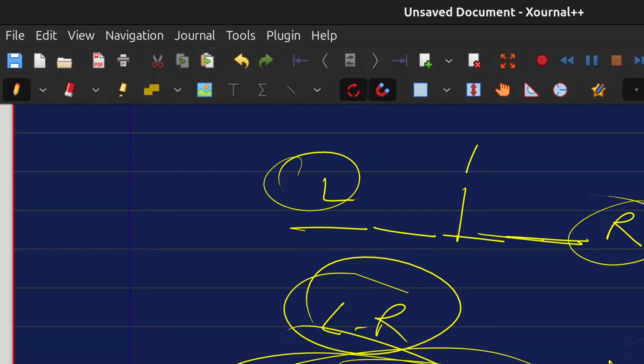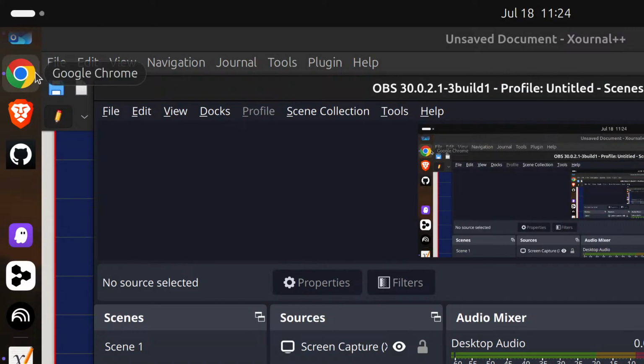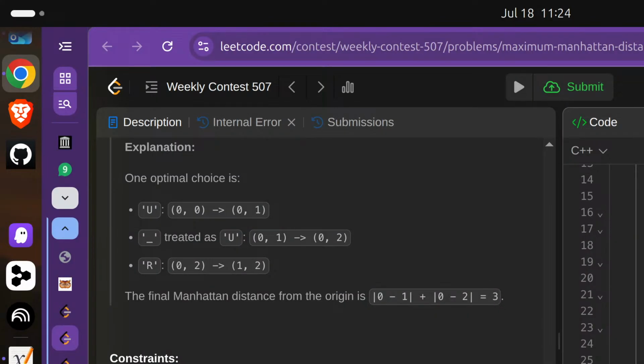So what engineers do is they perform something known as a null check. Essentially, they try to hold the nozzle in a neutral position, and then once that is confirmed, provide small commands to the nozzle to deflect it. And if the responses are deemed to be normal and the position is correct, we can be rest assured that the rocket will obey every command that is issued to it by the guidance software.